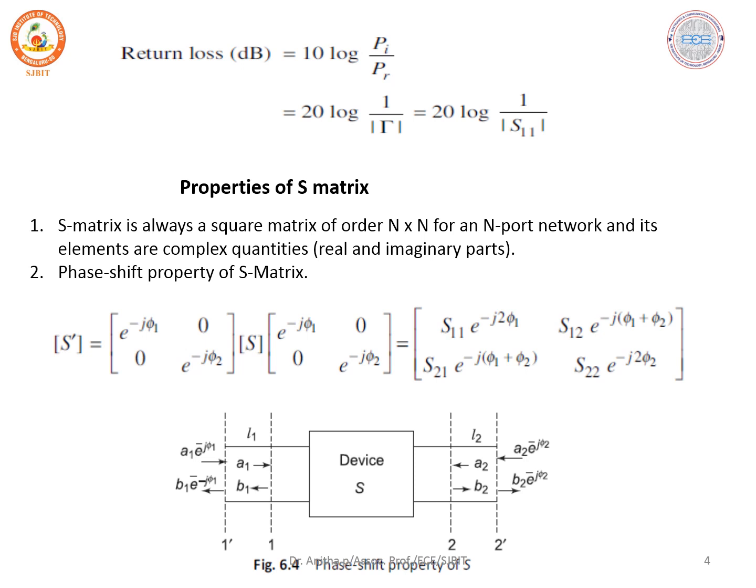So that is accounted over here, e power minus j phi 1 and e power minus j phi 2 at the S11 and S12 values. It has an effect at port 1 and port 2. Similarly, multiplied with the S matrix of the device, and again you multiply with the phase change which has occurred at port 2 due to the change in reference plane.